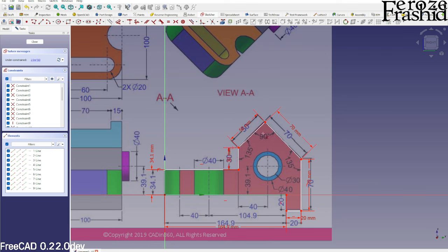I guess there would be the angles here because I don't have the length of this line. So let's select these 2 lines and hit D on the keyboard. That gives you the option for a 90 degree angle, because you already have the dimensions in there. That's the smart dimension.